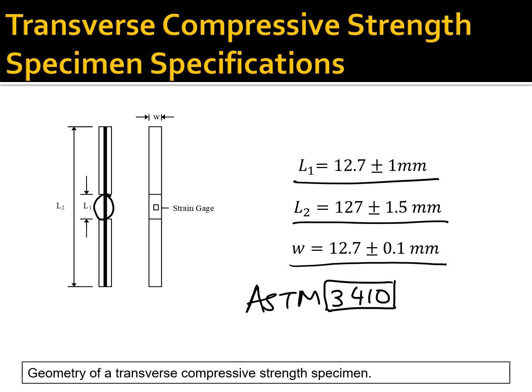And in the 0-degree ply or the longitudinal compressive strength test, we use 16 to 20 plies. So that's what was used for the 0-degree plies. But here now we're going to use 30 to 40 plies when we have 90-degree plies. Again, because we're using a thicker laminate here, we don't want it to buckle, so that it can take a higher load before it buckles.